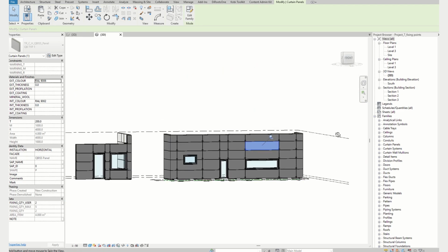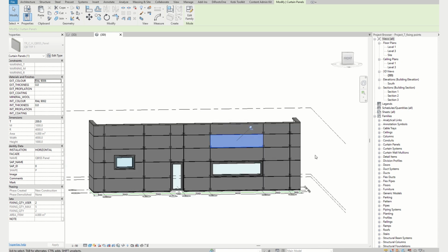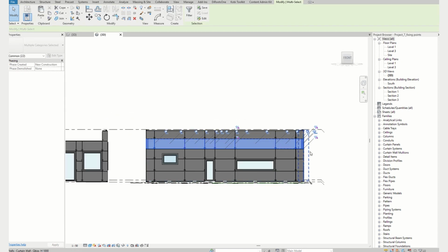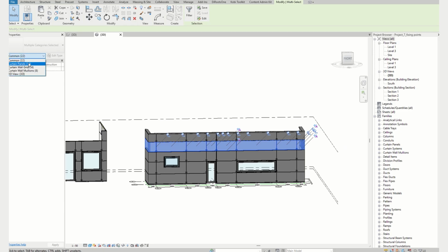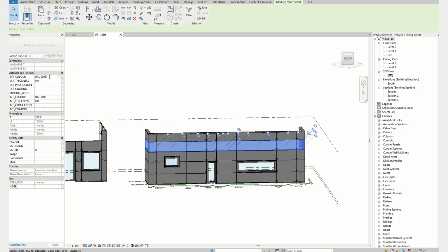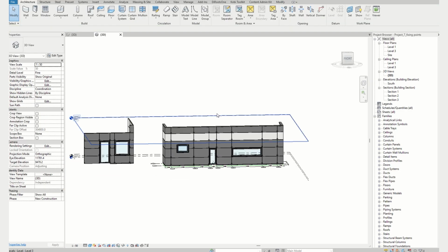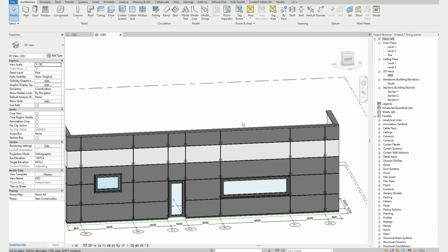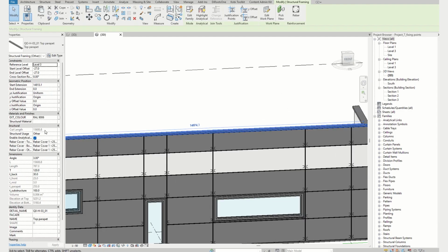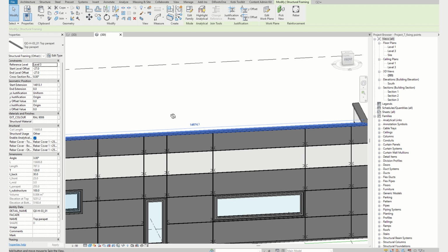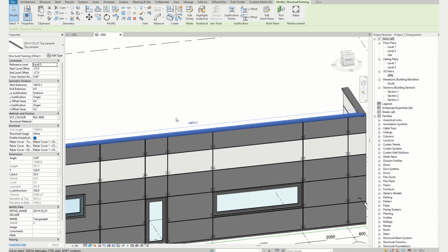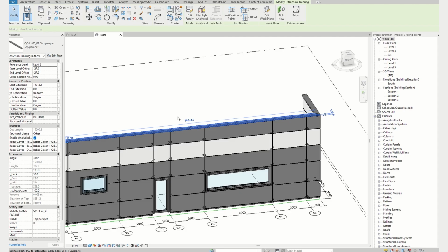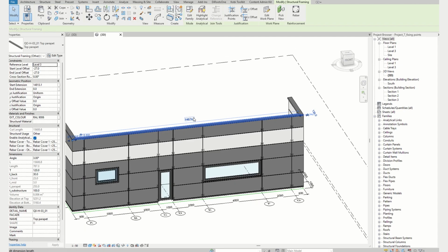Can we make only one row of panels a different color? Sure, let's just pick them and select different color material. Let's choose 9002, the white color. The same is for all facade elements with external color property. What if we need a color that isn't on the list? We can create new Revit material, but we should check the color chart in Qbiss book for available colors.